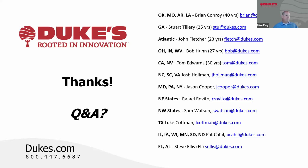Caitlin? We did have a question during the webinar. Someone asked, is it typical to perform CCTV after root control is applied in order to verify that roots are gone? Yeah, that's a pretty common practice. I spoke with one of our main guys earlier on this, and the number he threw out is probably something like 20% of clients have some sort of mechanism to go back. They may do it themselves. I know of cases where we include that even, but I think the broad answer is yes, that sometimes is done. And as more confidence is gained over time, that probably decreases.